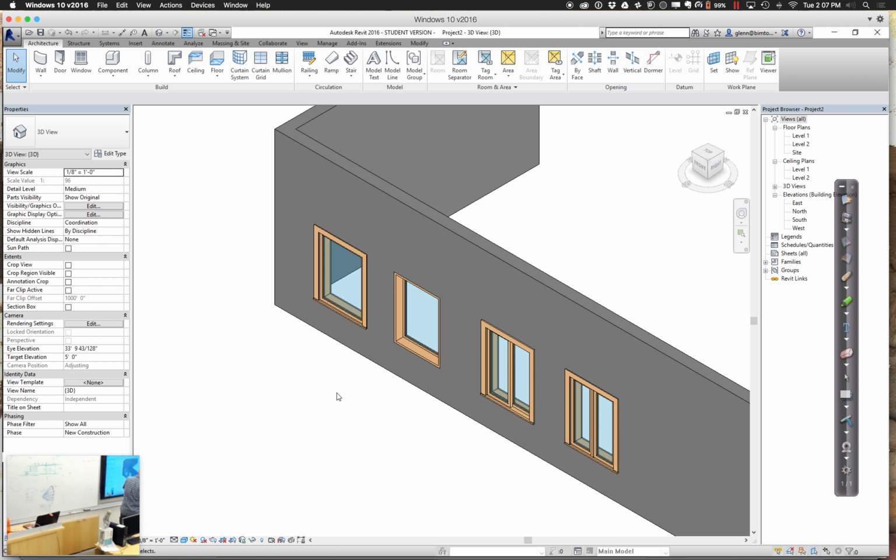Okay. If you were thinking about this in a very practical sense, I do a lot of residences, so I'm always thinking about fire egress and having to be able to get people out of bedrooms through a window. In that case, the fixed is no good. The casement window or the double casement are good. You get to count the whole area of the window as being a possible evacuation route. The slider window is limited, in that you can only count half of it, because even when you open it, only half of it's available. So lots of different choices in terms of windows.